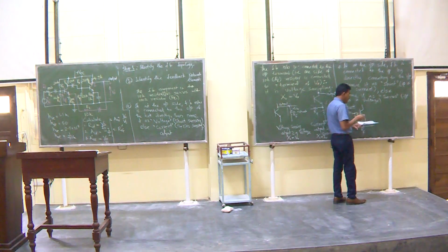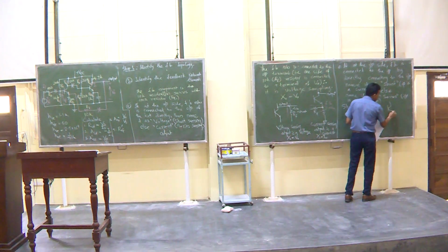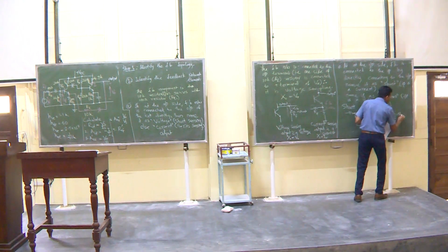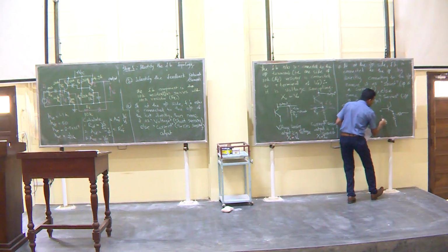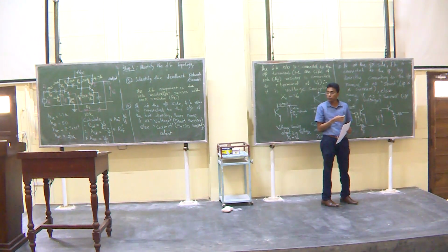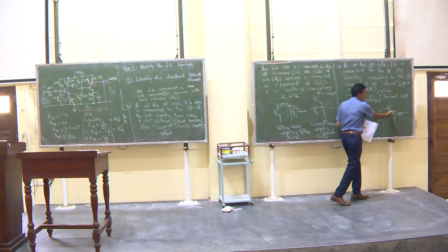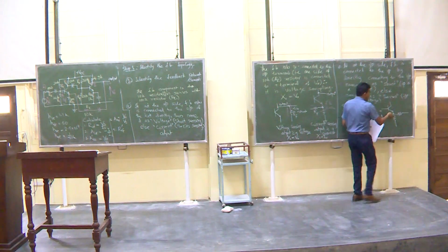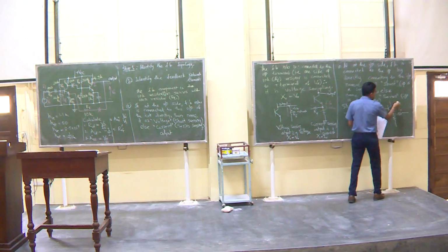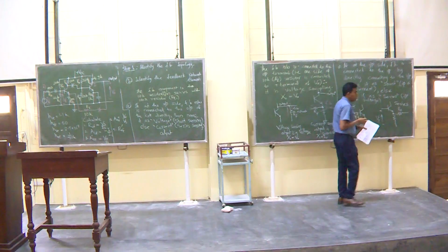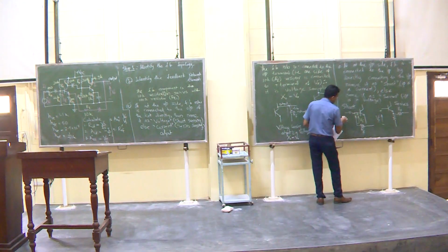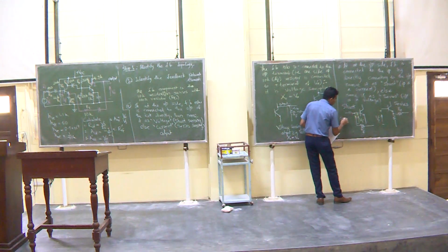Or else the other way is, you have the input side like this and you connect the feedback not to the input, but somewhere else, not directly to the input. This is not the input, right, input is here. So, you connect it somewhere else, this is RF, this is what we call series mixing.